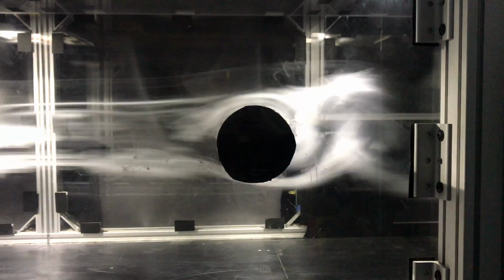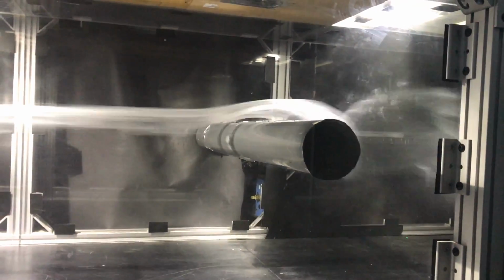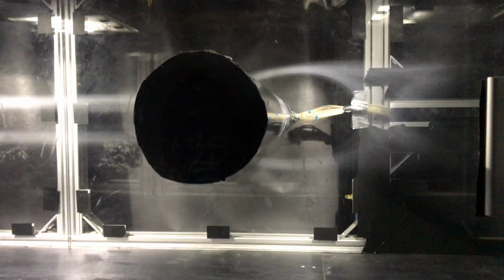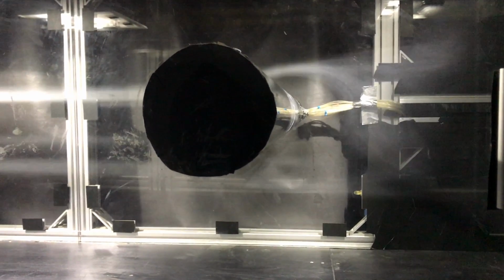The video shot at 200 RPM validates the team's prediction of an oscillating Kármán vortex wake with large vortices easily visible in its smoke. At 600 RPM, the wake behaves significantly differently, with no large vortices and a thinner wake. This led us to conclude that the boundary layer had undergone turbulent transition.